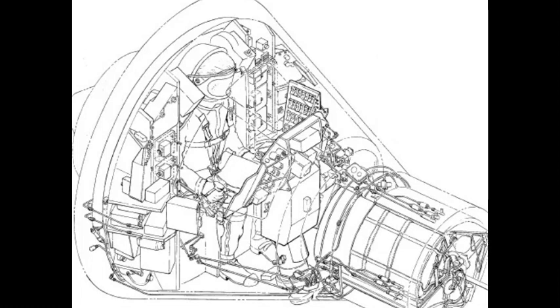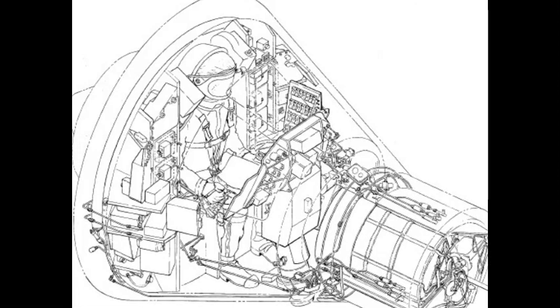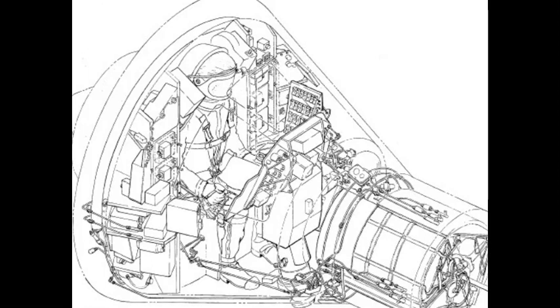An explosive charge initiator is located in the upper aft corner of hatch and is linked to a release control arm. A pressure valve, located below the initiator in the lower aft corner of the hatch, enables pressurization of the capsule during capsule ground checkout operations.